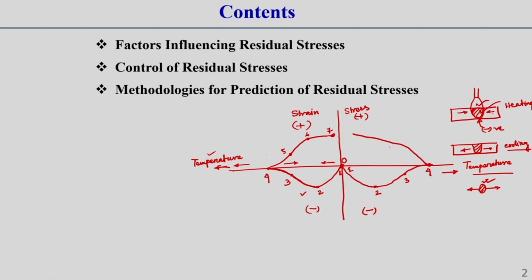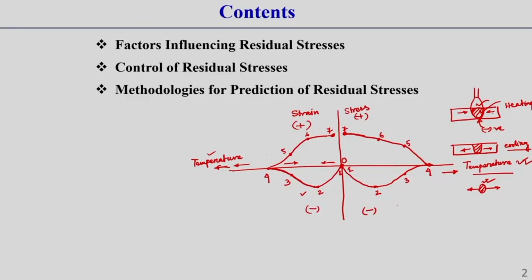This is how we can write it. Here I am writing 0.5, 0.6 and 0.7 around room temperature; I am just drawing like this. So you observe how this stress strain curve varies with temperature. That means you should get the idea why, in the weld zone, after cooling the stress distribution is tensile in nature. This is called the stress strain temperature curve.